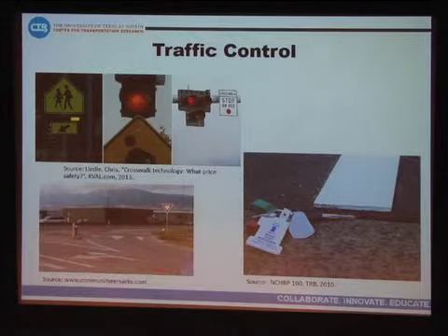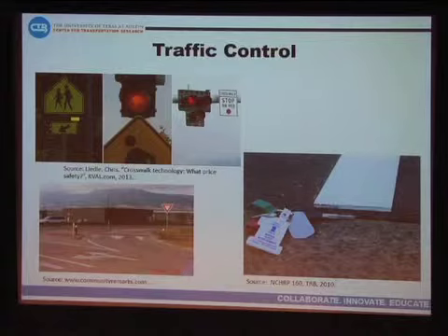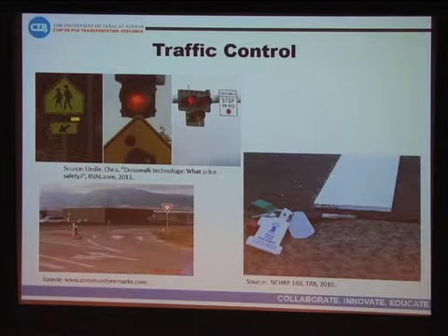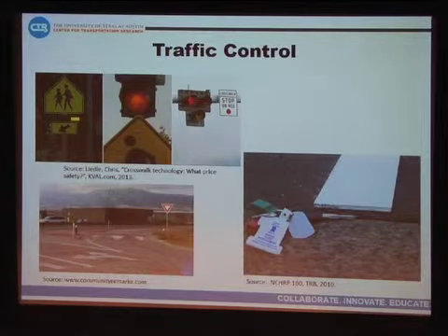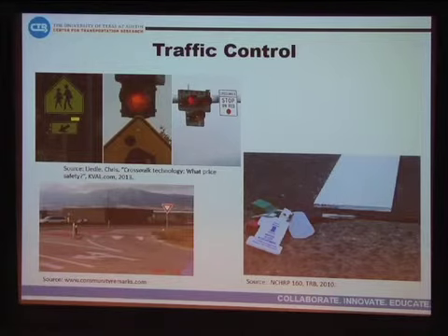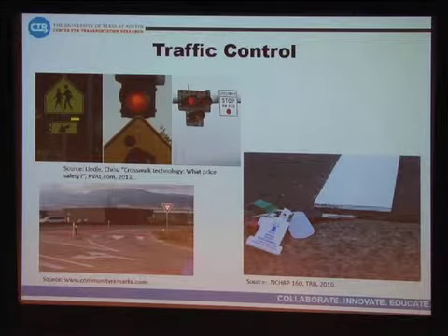And then we have some of the other devices, including pedestrian activated beacons or hybrid beacons. We have the rectangular rapid flashing beacons, and then some of the other treatments as well, like raised crosswalks, the implementation of sound strips or rumble strips to help alert the driver of an approaching crossing.